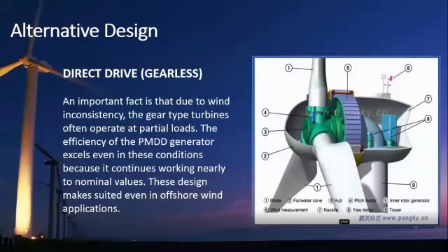Next, an important fact is that due to wind inconsistency, geared turbines often operate at partial loads. The efficiency of the PMDD generator excels even in this condition because it continues working near nominal values. This design makes it suitable even for offshore wind applications.